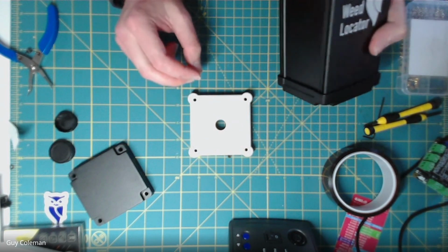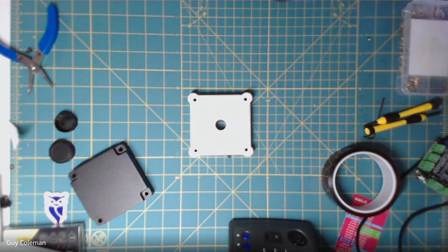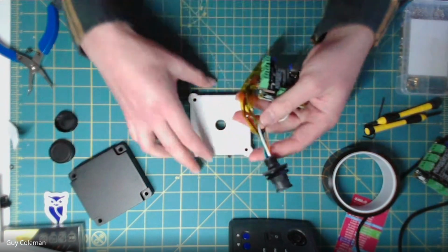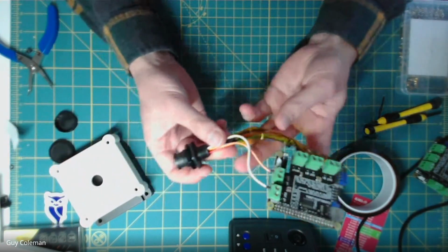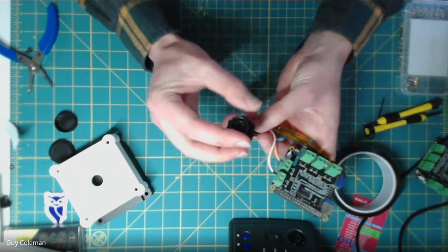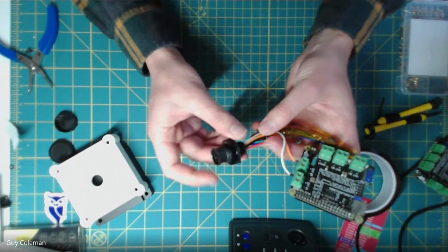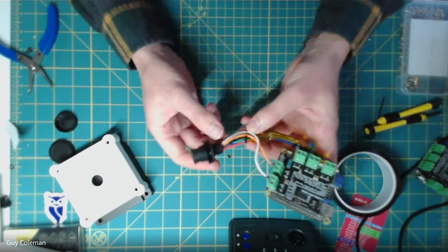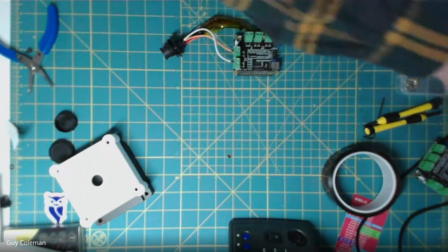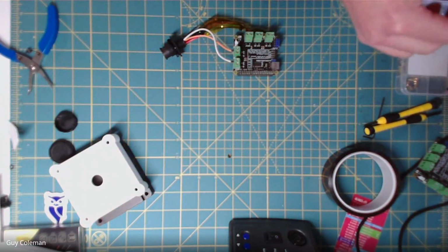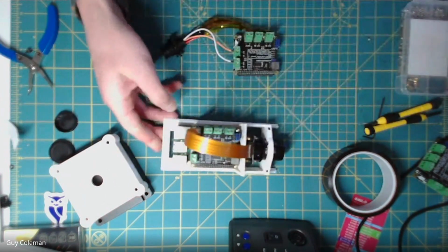The default connectors I've been using are these, Amphenol Fathom Lock, just because they're quite compact and also allow high current, I think up to 13 amps through particular connectors for the power. And also they're not too expensive, and they're quite nice to use. But this is, I guess, bringing this one back. So this is, of course, just all the hardware.